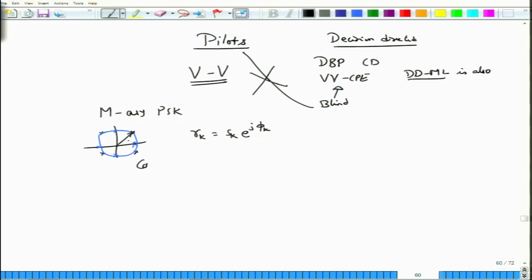So, these are also called constant envelope signals. Of course, noise will be present. So, what would noise do? Noise would take this amplitude and make it lie anywhere in between these values, right. So, it would make a bulge region around that one, and when you have finished looking at the phase and estimating the phase correctly, you are going to obtain this kind of a constellation.